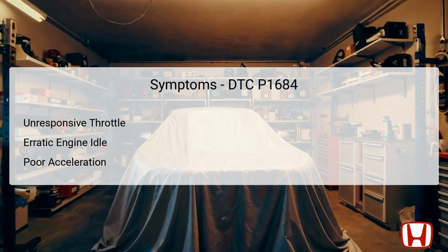When DTC P1684 is present, drivers may experience various symptoms that signify a problem with the throttle valve's return mechanism. One noticeable symptom is an unresponsive throttle, where the vehicle does not respond as expected when the accelerator pedal is pressed. Additionally, the engine may exhibit erratic idling.